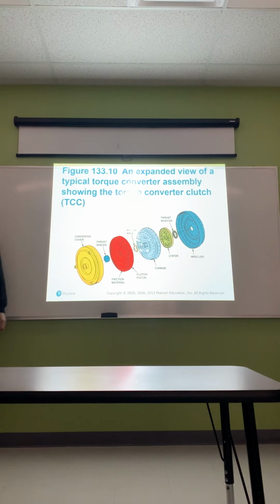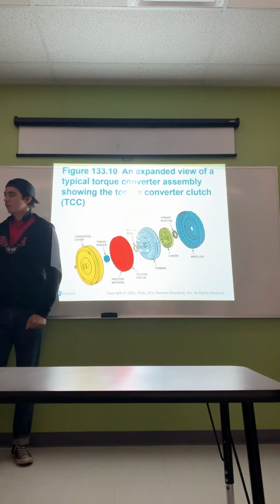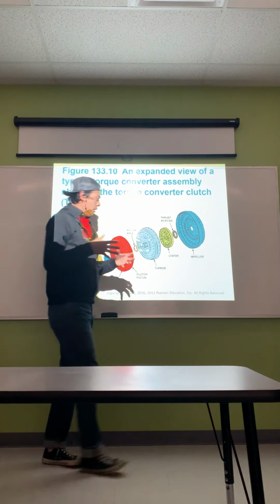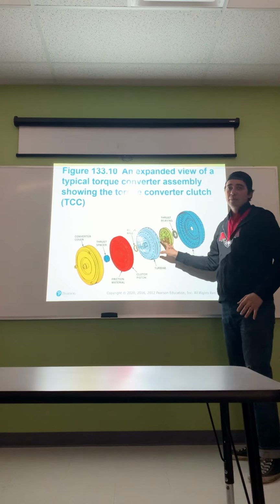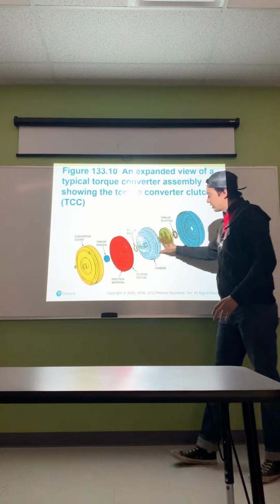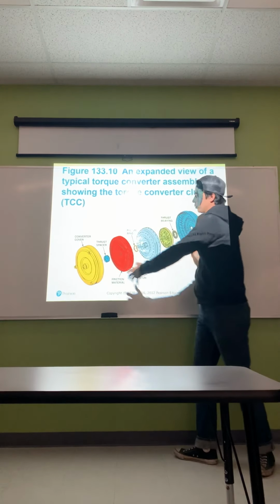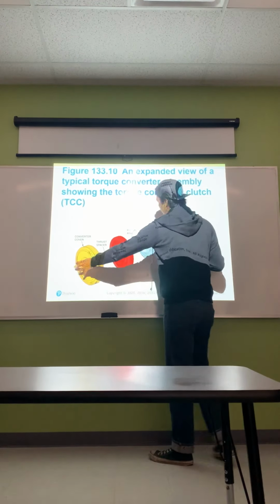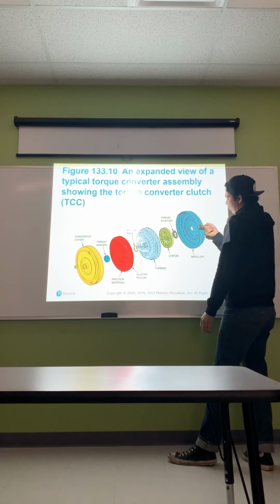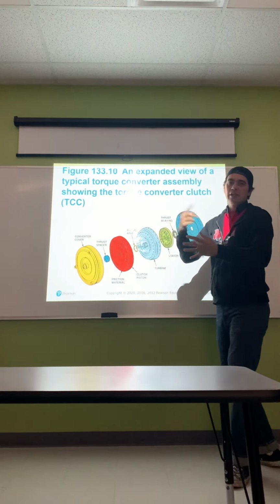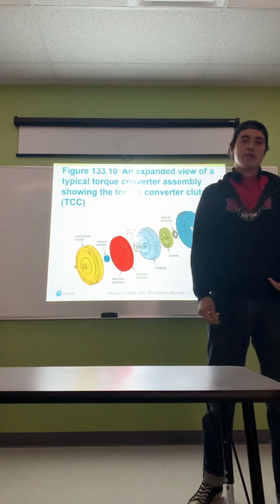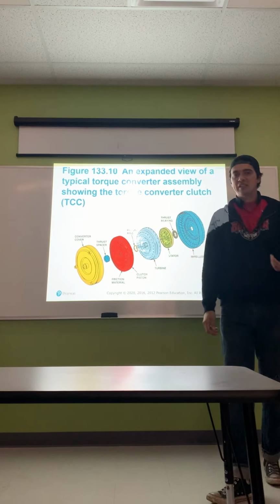An expanded view of a typical torque converter assembly showing the torque converter clutch. Now, all these portions here, unless you work in a shop that rebuilds torque converters, you're never going to see these. The reason why is this portion that's attached to the flex plate, this portion where the transmission input shaft comes in, all of this is enclosed and is welded up.